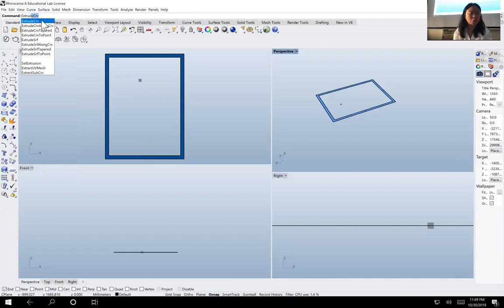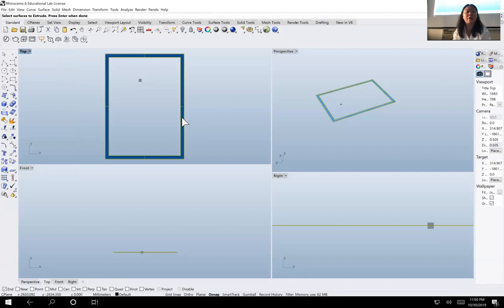You can extrude the curve, you can also extrude the surface. I'm going to extrude the surface, because I want a solid when I extrude, like a box. It's not a paper, you know. So I extrude the surface. Now I select, we need to keep talking to the computer, select the surface to extrude. I can select here too. I can select based on my floor plan, yeah?